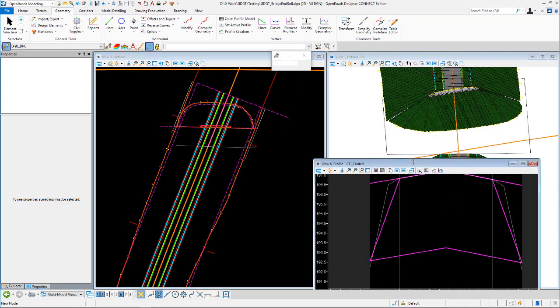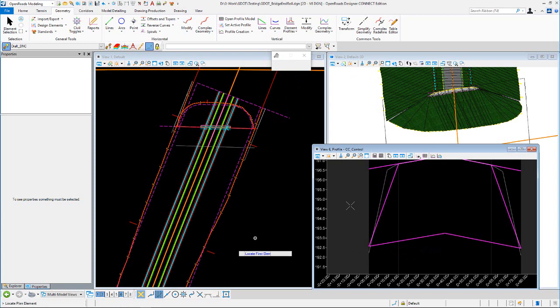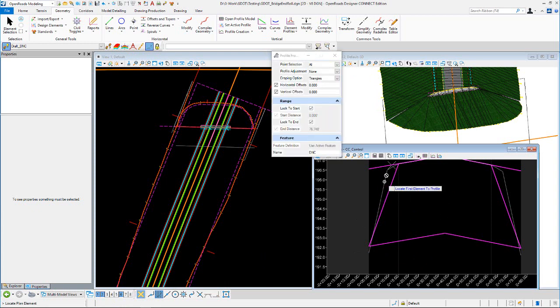And really, I don't know a good way to measure this slope. I probably should, but I don't. So, without doing some digging, and I'll have to do that later just to get this video done, if nothing else, you can look at your elevation and your offset there, compare them to the elevation and offset there, right, to get that slope at this skew. I came up with about 46.9 in this particular situation.